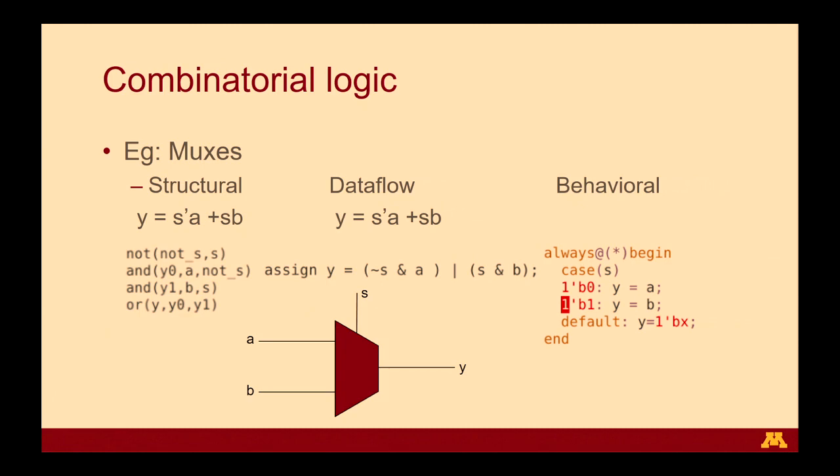So this is how memories are designed within Verilog: any if condition without an else condition, or any case statement which is incomplete. For any input condition which is not defined, the synthesis tool interprets it as a memory and will hold the previous state.